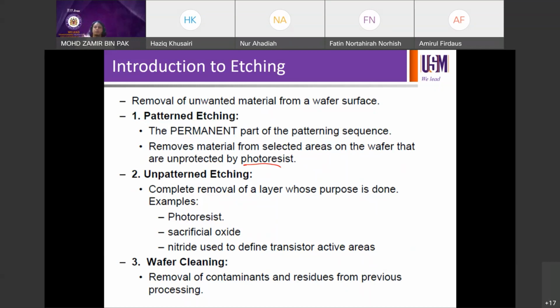Remember, resist is a polymer, so it has stability, certain temperatures that it can withstand. Some temperatures outside lithography can go up to say 1000 degrees C. That will definitely damage the resist and cause cross contamination. So resist will not be there forever. We only want it for patterning of the next step. So resist is not part of the device. It is just an intermediate step, or a dummy step.